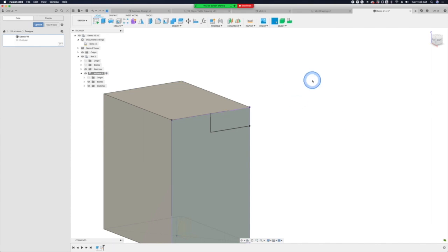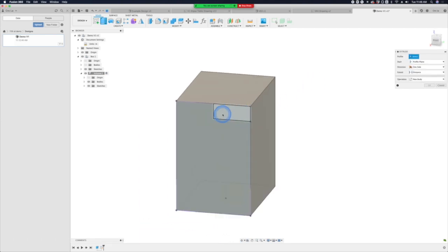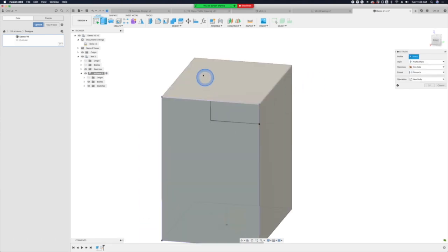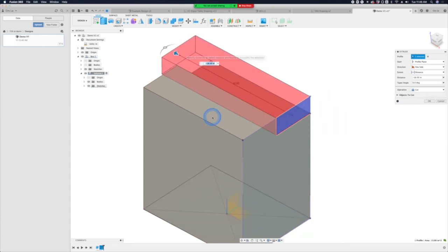All right, cool. So I'm going to finish that sketch now and go to extrude again. And I'm going to use this piece of geometry I created to modify this existing shape. I'm going to highlight this. If I do this, it automatically is joining to this geometry. If I take it away from that space, it automatically turns it into a cutting operation. And then you have a dialog box of which bodies you want to cut.